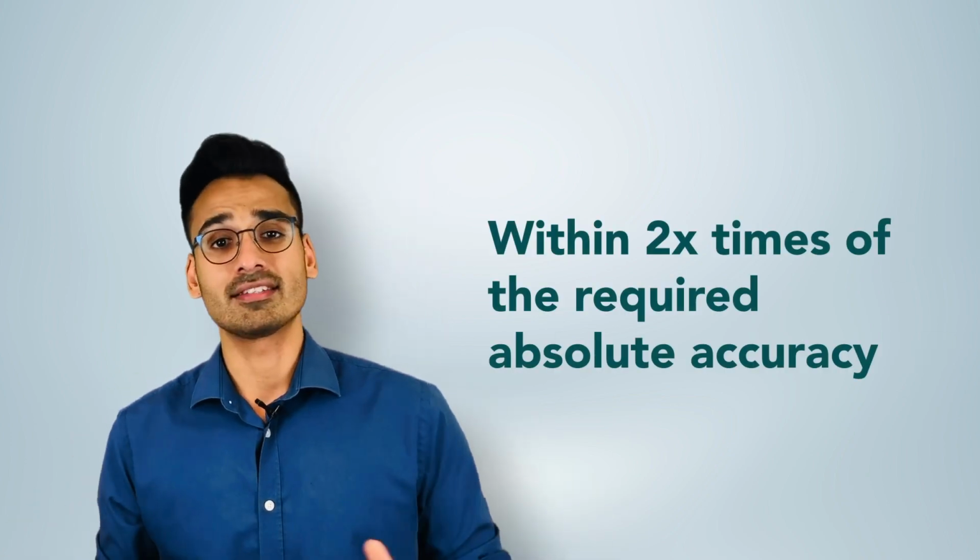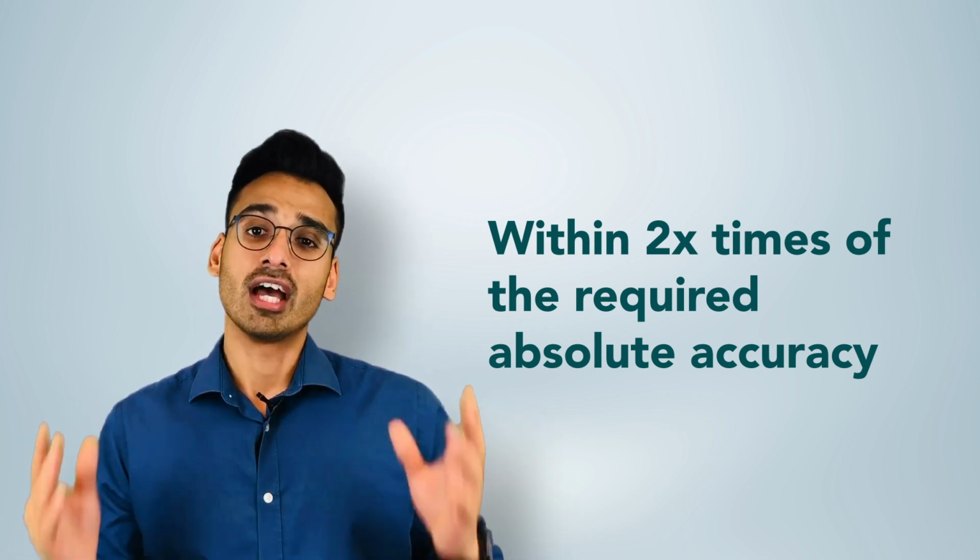For those types of georeferencing accuracy, it's important that your GSD is somewhere between 2x the required amount of relative accuracy. Again, we talk more about data accuracy in a separate video, but the key concept here is that GSD can affect both georeference accuracy and measurement accuracy, and it's important to understand the constraints around what you can and cannot do with GSD with respect to those applications.